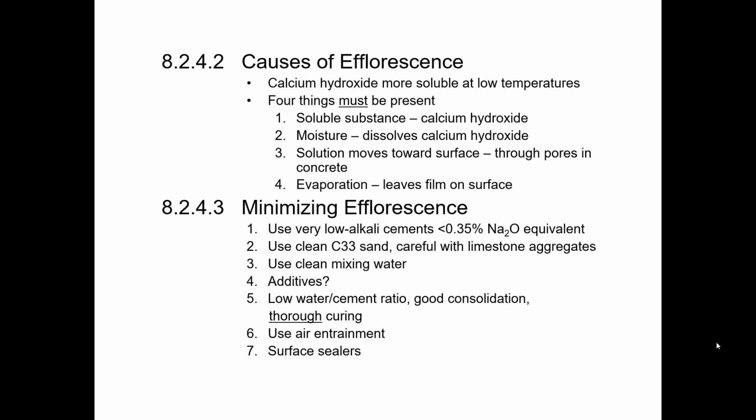Using air entrainment will help for the same reason that it helps eliminate freeze thaw damage. It gives the water a place to go without going all the way into the concrete through this entrapped air or through possible cracks that have been caused by freeze thaw stresses, internal stresses.